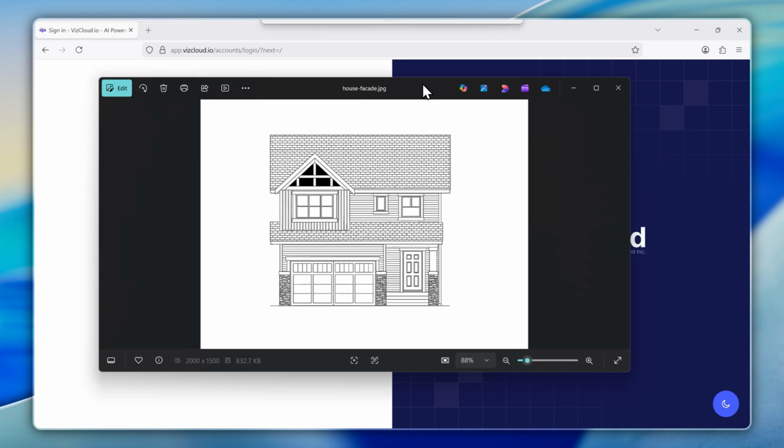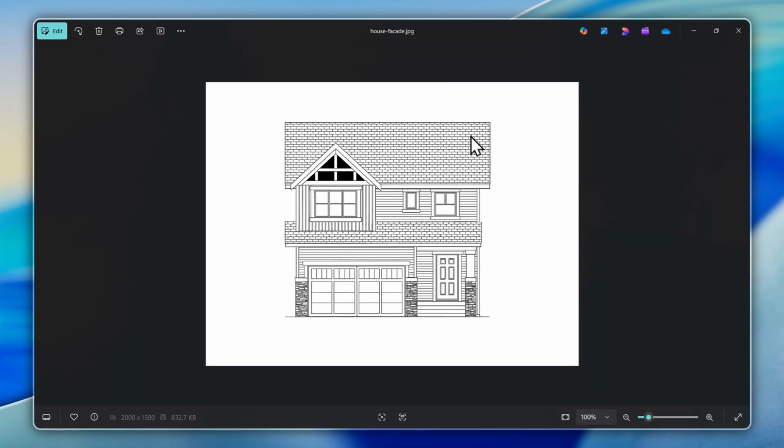So you can see our file right here that we've prepared. I'll go over some important points about it. First of all, when you take your screenshot, leave a little white space around the design so the AI can use that space to fill in scenery and a background if you choose. We also recommend removing any extra lines, arrows, measurements, and anything else layered over your design so that only the elevation is shown. Try to use a thicker black stroke on a white background for best results.